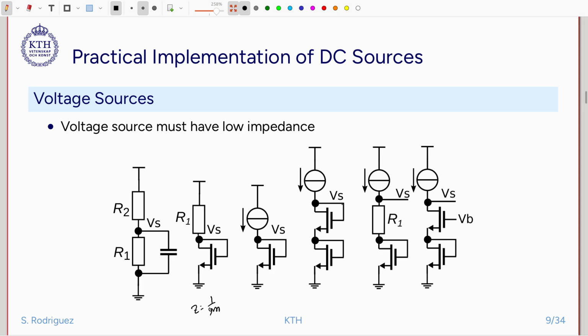We can have a variation also: a diode connected transistor and a resistor in series. Something else that we can do is use a combination of diode connected and triode, putting the transistor in triode as here. So this is basically equivalent, just that this transistor has been placed in triode. But typically we will be using something like this in our circuits most of the time, or like this.